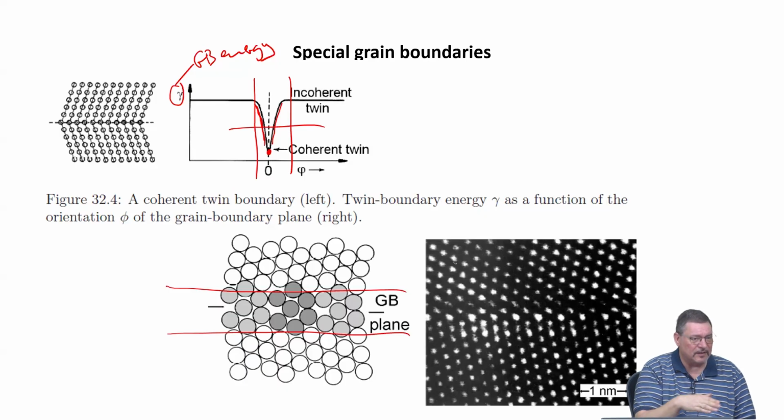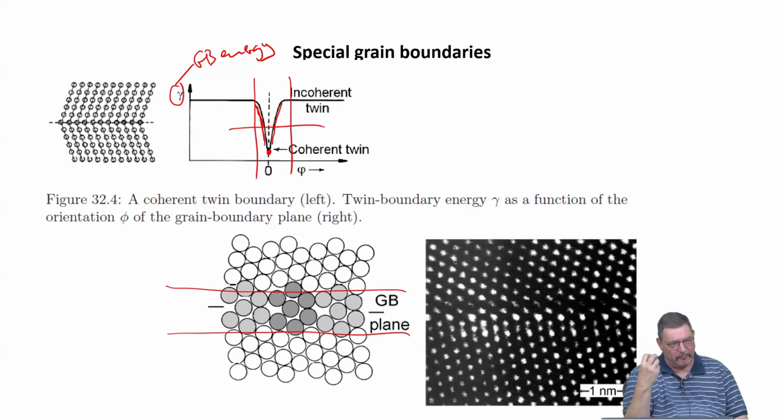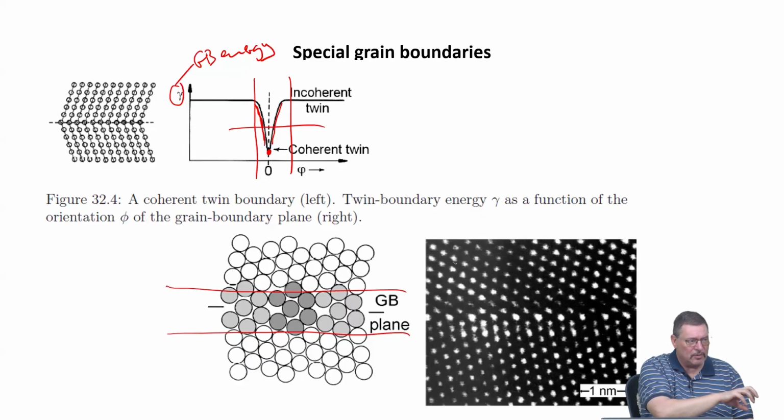So this means that the Gibbsian description of having a mathematical 2D plane as a boundary between phases, for example, can also be applied to the grain boundaries or to phase boundaries. But if we think of a diffusive process, we really have to go from the continuum description based on Gibbs to the local atomistic description, and then we have a grain boundary zone, a slab of a certain thickness.